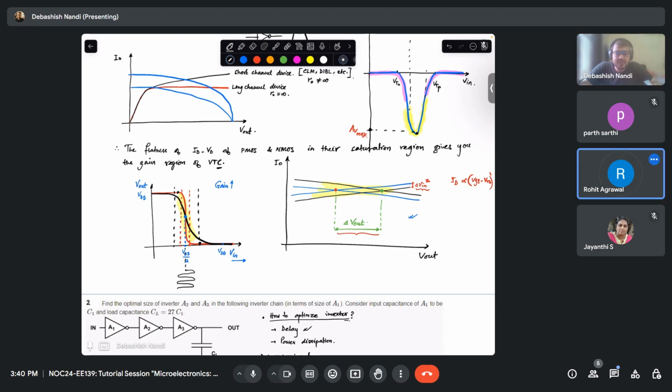The point is, in case of the red curve, you cannot amplify a sufficiently large analog signal. Your signal amplitude has to be very low. Otherwise, it will change the bias point and shift it to this region where you do not have any gain. For that matter, your signal will be simply lost.